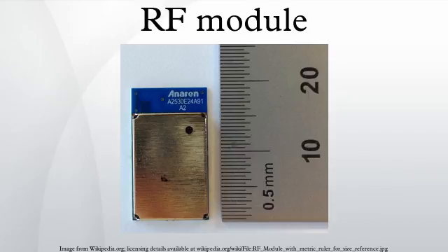Correspondingly, increasing the receiver sensitivity will also increase the effective communication range, but will also potentially cause malfunction due to interference with other RF devices. The performance of the overall system may be improved by using matched antennas at each end of the communication link, such as those described earlier. Finally, the labeled remote distance of any particular system is normally measured in an open-air line-of-sight configuration without any interference, but often there will be obstacles such as walls, floors, dense construction to absorb the radio wave signals, so the effective operational distance will in most practical instances be less than specified.